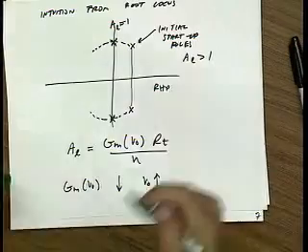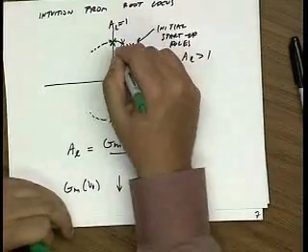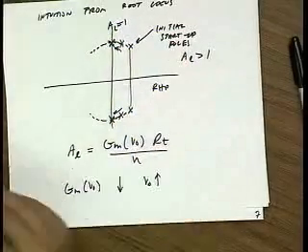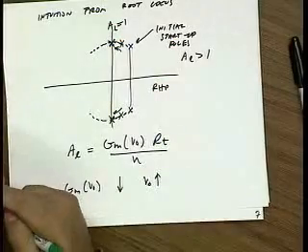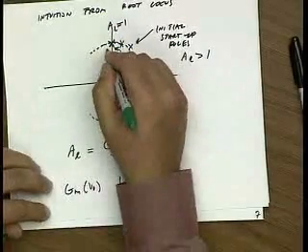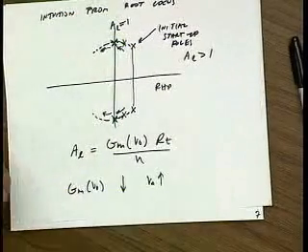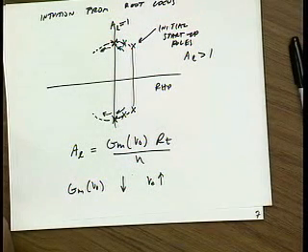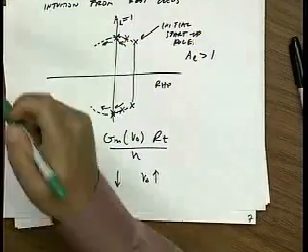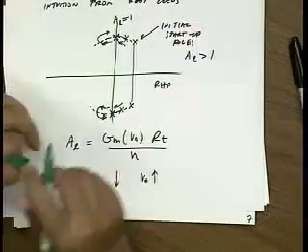Well, that we already discussed. So if somehow the poles move to the right half plane, there's a tendency for them to move back, because the amplitude gets bigger, the gain drops, and then they move back. Equally, you could say, what happens if somehow they move into the left half plane? Well, that would cause the amplitude of oscillation to decay. And as the amplitude of oscillation decays, the GM gets bigger. The GM gets bigger, that tends to push the poles back onto the j omega axis.